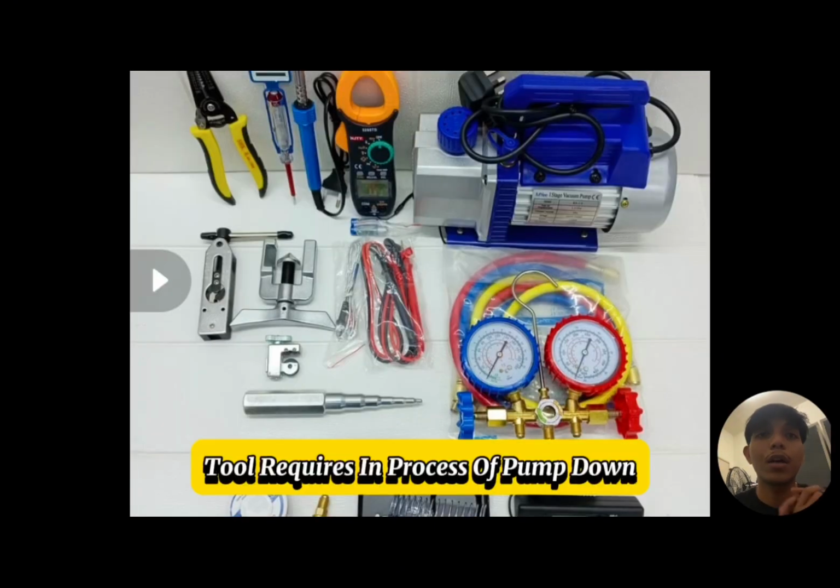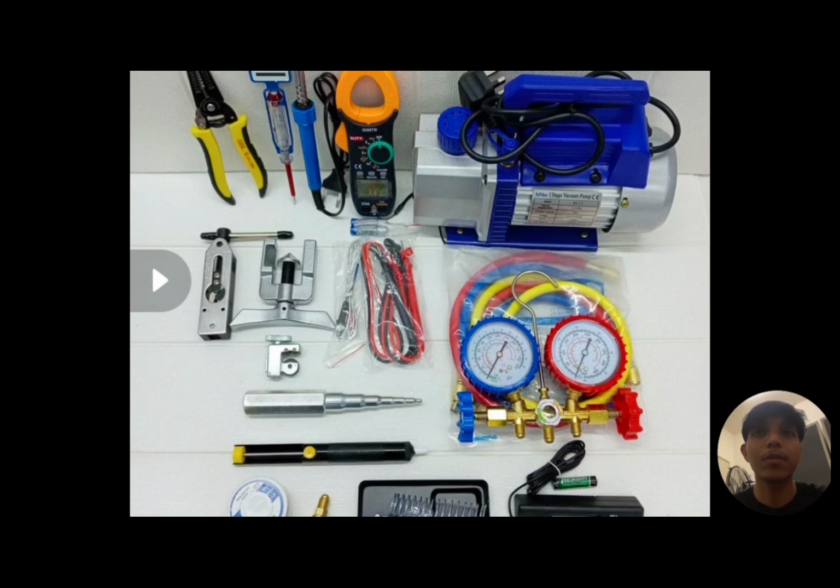So today I want to present to all of you about the pump down in the aircon unit. The first thing we need is a manifold gauge set. The second is a vacuum pump. Then we use a refrigerant recovery machine, a refrigerant scale, wrenches and a socket set. If any line needs to be detached and reconnected, we use a soldering or resin kit. And the last are safety gloves and goggles.